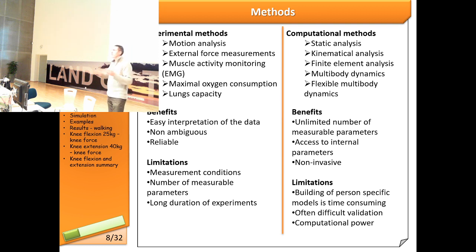So with multibody you can analyze something that can last even hours or minutes, but you have a small number of actual variables that you're solving for. So you have some amount of bones, some amount of external foreign objects, and you're solving what happens between them. And if you combine finite element and multibody, you can get the mix called flexible multibody dynamics, where you have some elements which are used to determine the stresses, where you are interested in the stresses, and those models are finite element based, or some kind of model reduced finite element models. And you have rigid elements which do the rest,